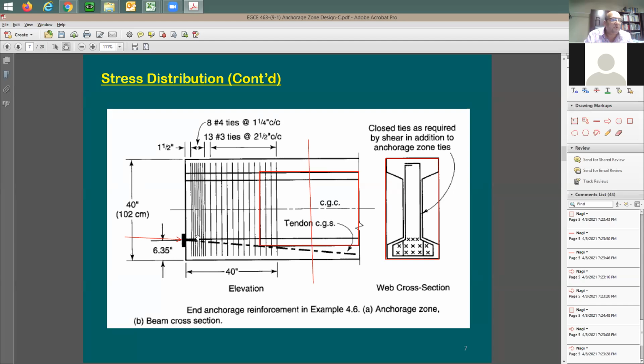And this location is also critical because if you are going to be having any relative movement, very small movement of this bearing block, or bearing plate, to the inside, it means that you're going to see here some losses in the pre-stressing. You don't want this to happen.